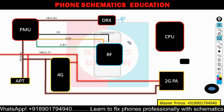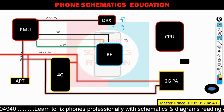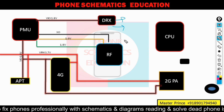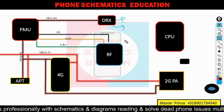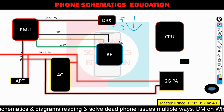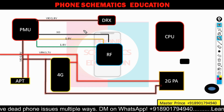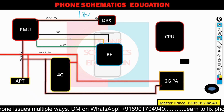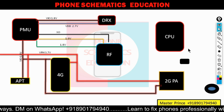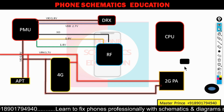But nowadays, each and every phone has this IC. So when you talk to someone, you can use the internet services also, because internet services shift to the DRX IC, your secondary. Now this IC also needs a voltage to run, a 1.8 volt. Now second, anything more? Let's see. There is another voltage called 2.7 volt. So let's see these two voltages in the schematics and how to test.